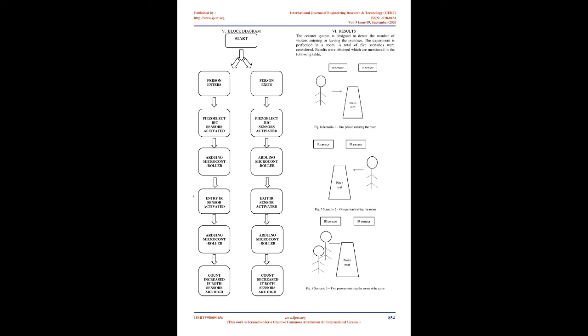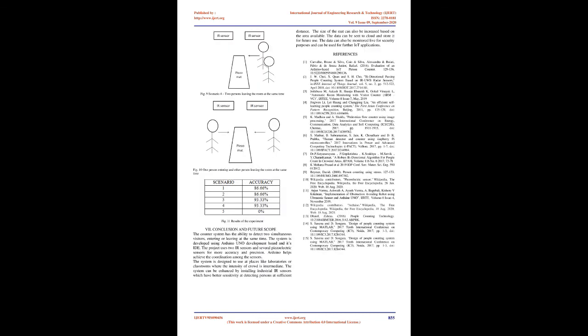Digital. The digital pins are numbered from 0 to 13 on the Arduino UNO. They are used for both digital inputs like accepting data from a digital sensor and also as digital outputs like powering an LED. Reset button. Pushing the reset button restarts the code uploaded to the board. Main IC. The black cuboid with metal legs is the most important part of Arduino, known as an integrated chip or IC. The IC used in Arduino UNO is the microprocessor ATmega 328P.